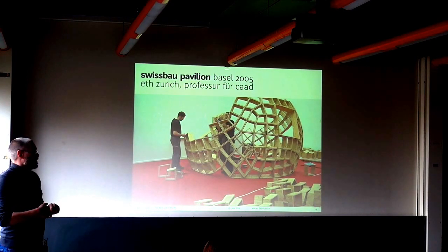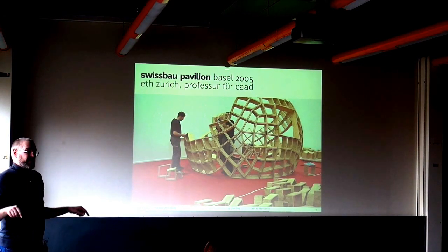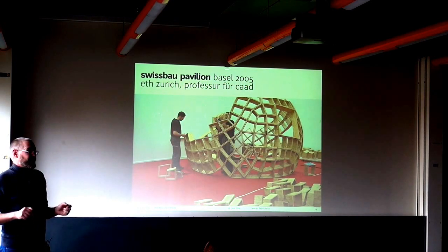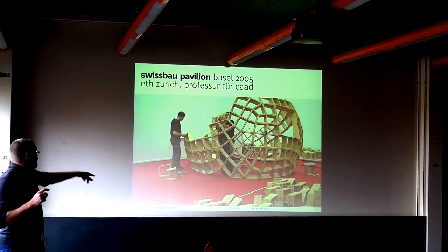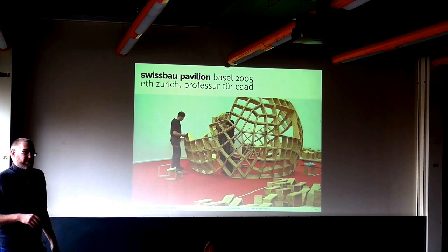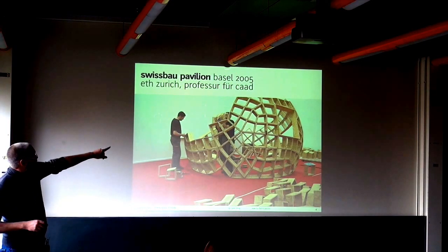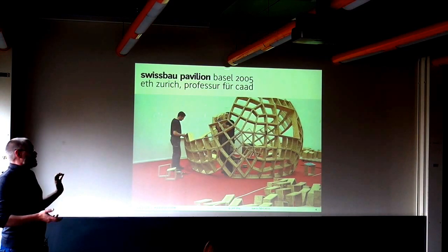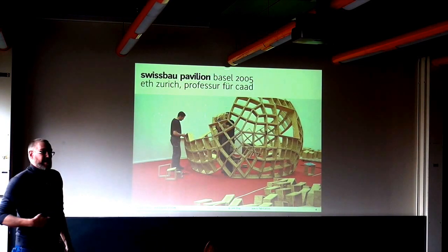But it's really just 2 cuts with a radius, 2 cuts with a mitre, 2 drilling holes and 2 notches where you can drive in little dovetail connectors in the corners to build those quadrilateral frames, which are nicely numbered. And if you stack them one on top of the other in the right order, you get this nice little sphere. And that was the trick, had those rectangular or actually quadratic openings there. And this little mesh had to align itself with the openings. That was my part of the thing.